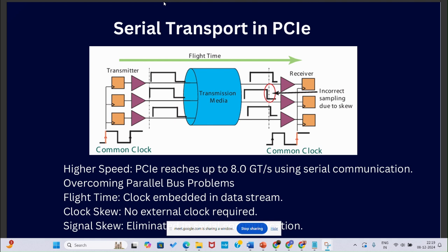Basically, they have some flip flops and a mux on the receiver side. As I told you, in the first picture, where the north and south bridge was there, you can see the slot clock there, right? The same clock you're giving to both the north bridge and south bridge, right? So this 33 megahertz clock is used to recover the data because both you and me sample the same. We are both synchronous, I mean, we both are working at the same clock frequency. So if I put the same clock to the flip flop and try to recover the data, I can recover it. So that clock will feed there, and from there we try to recover the data.